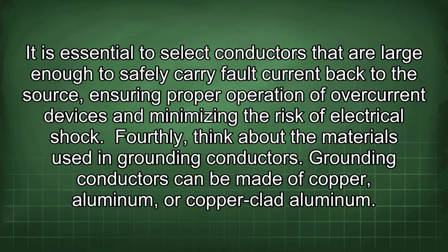It is essential to select conductors that are large enough to safely carry fault current back to the source, ensuring proper operation of overcurrent devices and minimizing the risk of electrical shock.